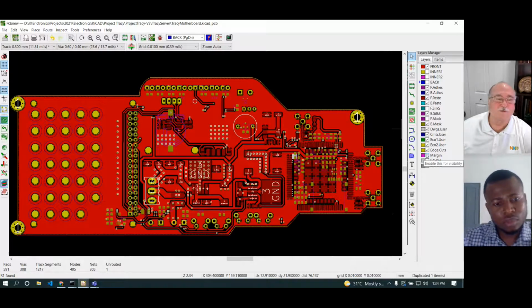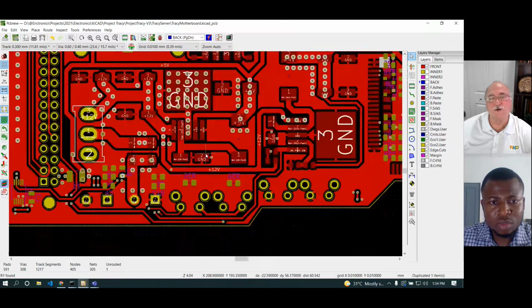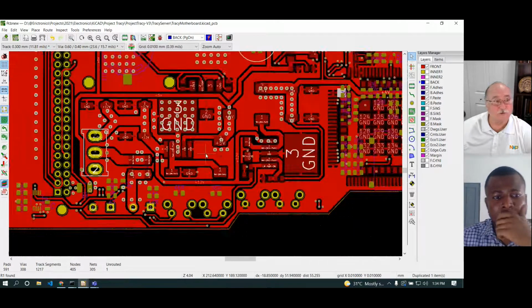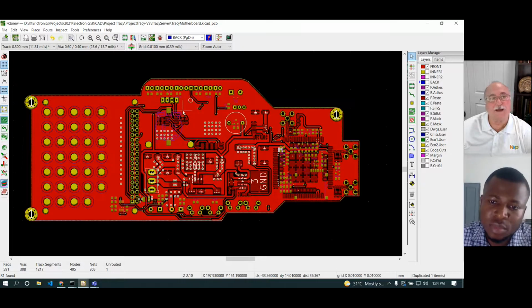I'm seeing what are probably waterfalls, as we talked about before, with interleaved power and ground where they're needed, or adjacent grounds next to the powers, in order to create more z-axis paths to connect the dielectric between layers 1 and 2, and the dielectric on layer 4, and in a lot of places between layer 4 and 3, because we use the ground flood as the bounding layer or the unbroken conductor that we use to manage the power distribution.